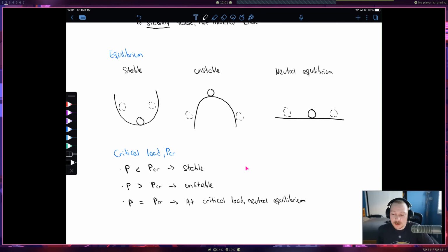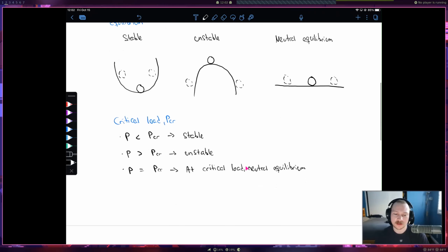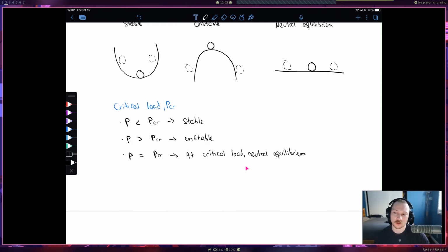Okay, so there is an equation for this, and it's only going to be applicable for a long column, and we still need to define what's a short column, what's an intermediate, and what's a long column, because right now that's really vague. But there is an equation for long columns. It's called the Euler buckling load equation, and we can use it for long columns to estimate when this critical load is going to take place.